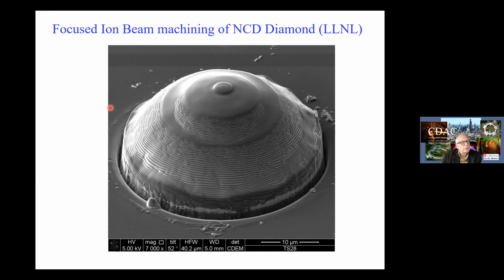Well, one of the first examples of that was the classic work by Mao and Bell in the late 70s using SEM. You could actually see flow of diamond on the surface by SEM. And I don't know if people have gone back to that relatively simple method to look for plastic deformation. We have a paper on yield strength of diamond, which I did with Mikhail Ermets, and it's rather low. What was your number, Reini? I think it's 1.3 megabar. 130, okay, so that would be like 65 GPa shear strength. Versus the simple model, which is 90 GPa.